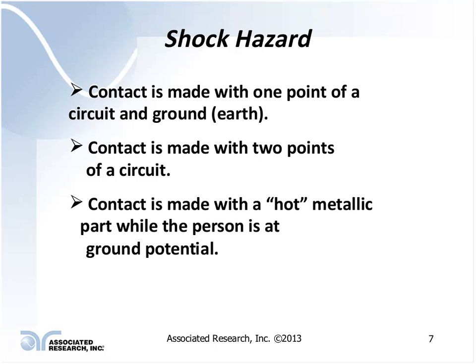If you have a product that is designed to be connected to Earth's ground, and you plug it into an outlet that is not grounded because somebody's either broken off the ground terminal or used an adapter where they're plugging it into a receptacle that doesn't have a ground connection, or they're using an extension cord where there's no ground, that could just have normal leakage current flowing through the enclosure that could result in a shock hazard.